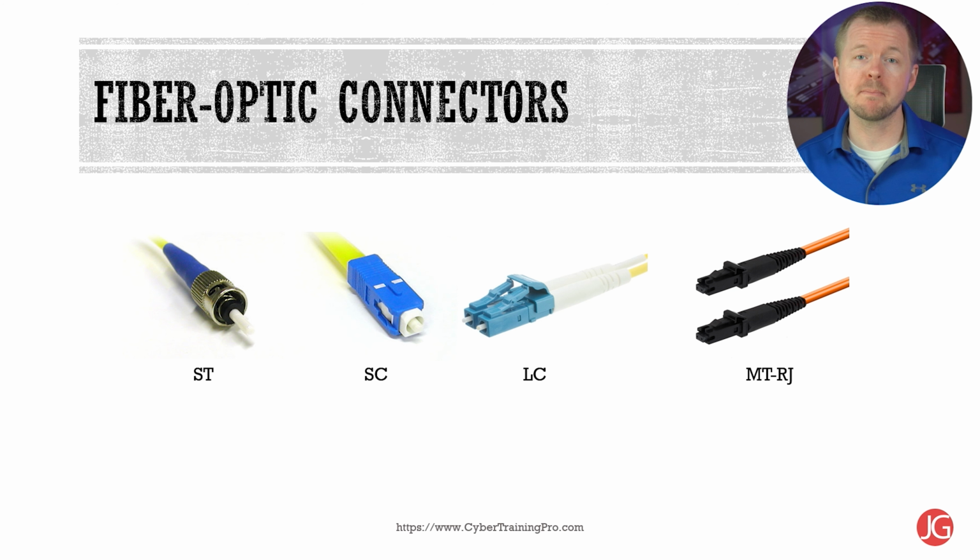Another quick point that I want to make is that with fiber, you need the right connector, but you also have to have a connection point called the physical connector, or the PC. The main 2 that you need to know about are the ultra physical contact, or UPC connectors, and these are polished extensively for a superior finish to reduce signal loss. And then angular physical contact, or APC connectors, add an 8-degree angle to the curved end and they lower signal loss even further.